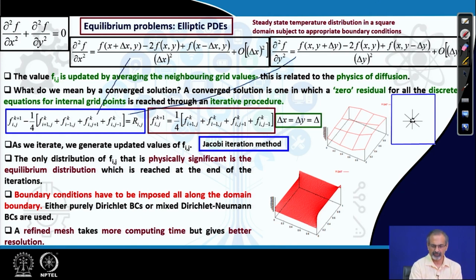these two inputs have converged here. Now, additionally we have used a superscript where some of the superscripts are kept at a level k, while for one we have kept it at k plus 1. And then on the right hand side we are putting r I j, which indicates a residual. So, what do we really mean to say over here? We mean to say that there would have to be an iterative procedure by means of which we will end up solving the value of f at each one of the grid points.